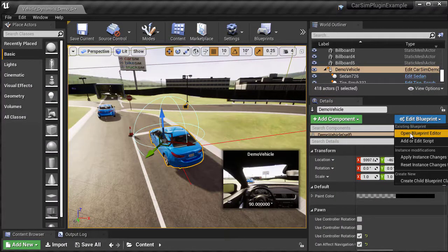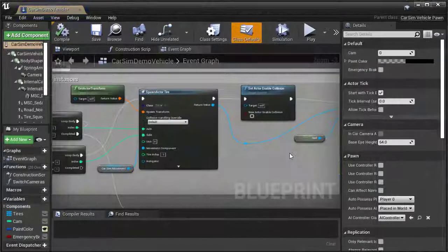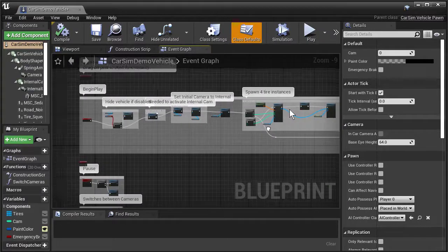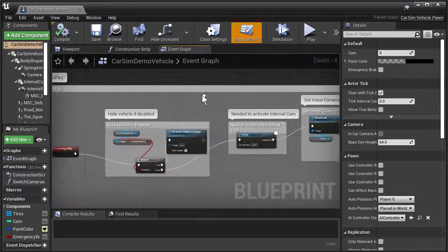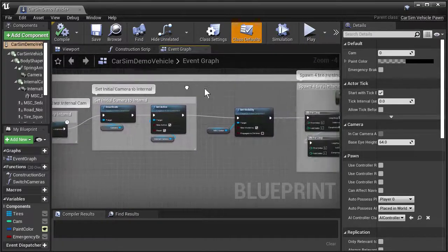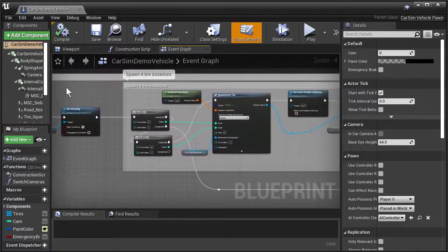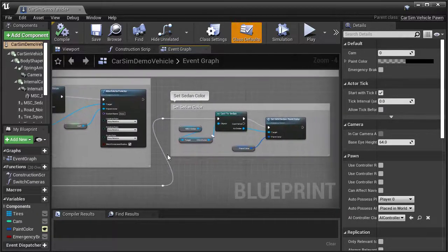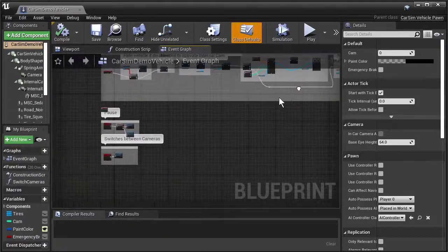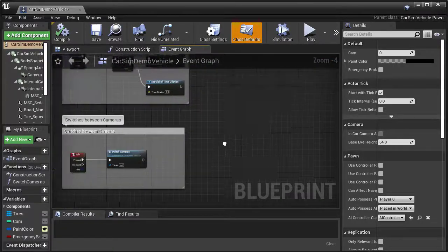Blueprints are an Unreal Engine visual scripting system that allows for rapid prototyping and complex behavior without requiring deep programming knowledge. The project includes blueprints to generate road, tire, and engine noise, along with spawning trailers and tires on startup for the vehicle and animating them. That's all driven by model data retrieved through the Solver Blueprint interface. There are extra cameras with switching behavior triggered by the Tab key. And of course, there is the vehicle body and interior.